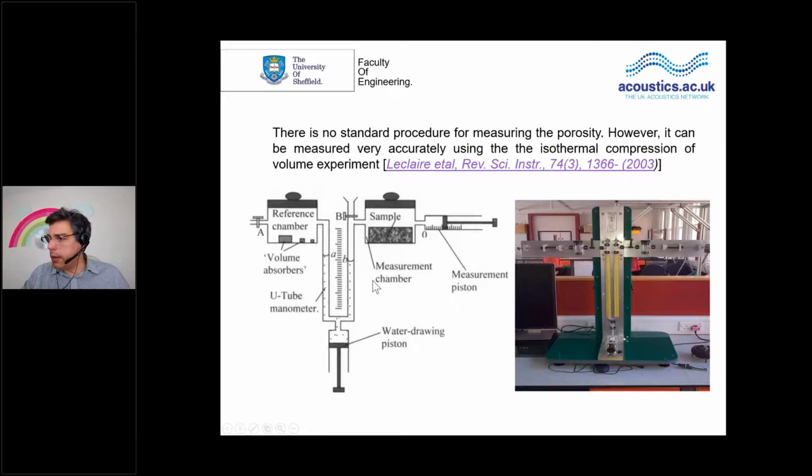Porosity can be measured using reasonably complicated BET techniques or techniques based on mercury injection, but it can also be measured using the method described in this publication, based on measurement in 2 sealed volumes.